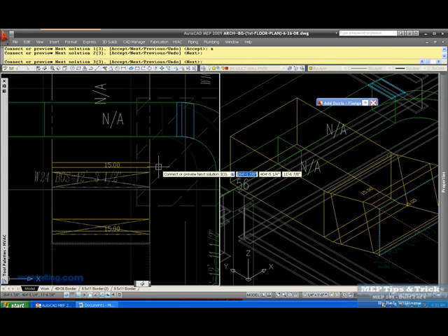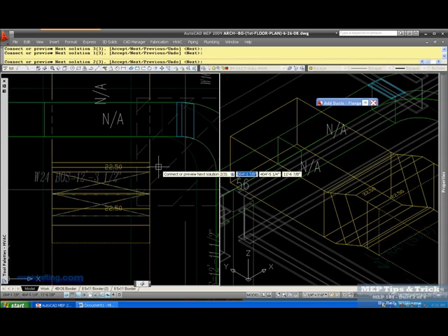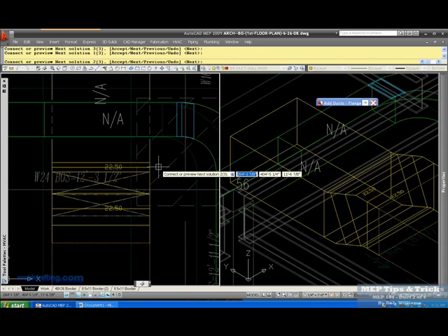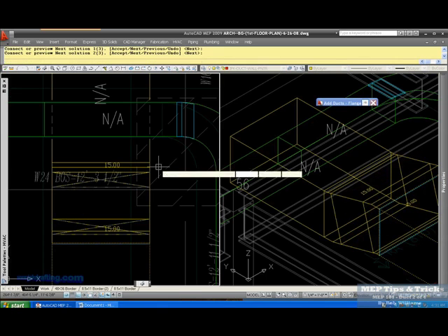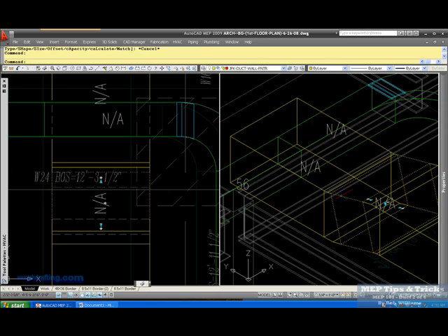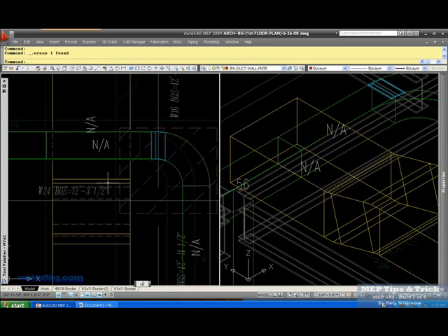You can look at it over there. 22 and a half looks to be about the, well, actually you can get to 15. Hit 15, hit A for accept, enter. And then what I normally do is I'll just detail that out, make it look like a fitting on top in plan view. And I'll show you that when we do some detailing.